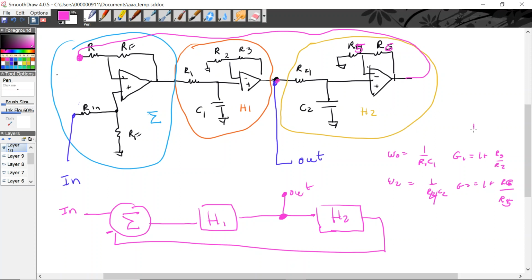I tend to choose 10K, but sometimes I might solve for a resistor that's over a meg. Then I go back and lower that. Talking about ideal op-amps, they can't drive small resistances. These are limited to about 40 milliamps. And large resistances like a megaohm and over have issues as well.